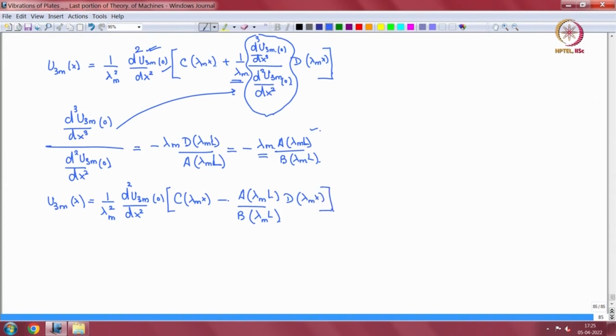Okay, that's the mode shape. It's indeterminate up to this constant, otherwise the amplitude constant is not known, otherwise the shape is known. So the shape is known. Okay, so this is a clamped beam. The clamped beam first mode looks like this, the second mode looks like this, and so forth, with slope 0, displacement 0.